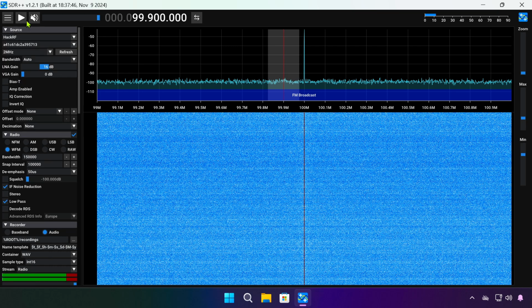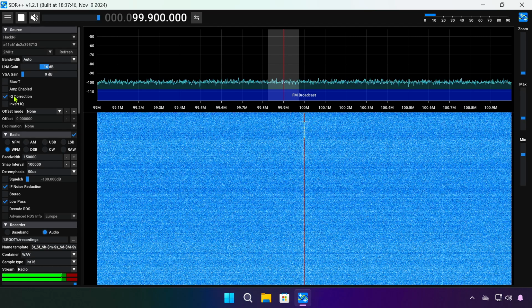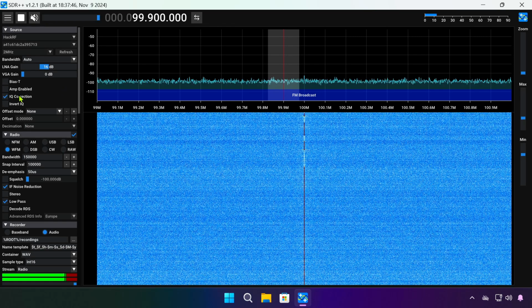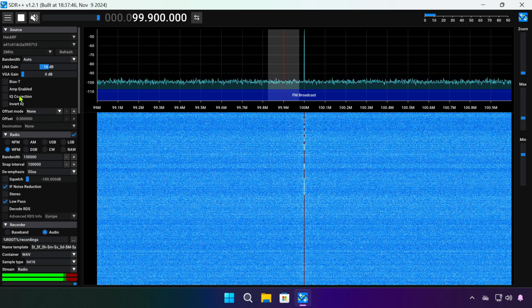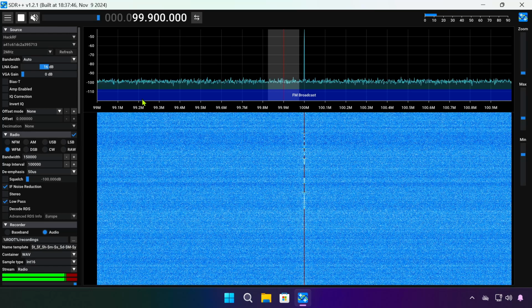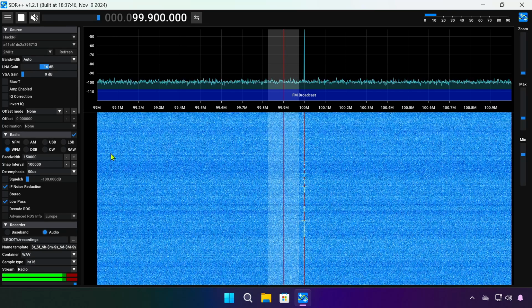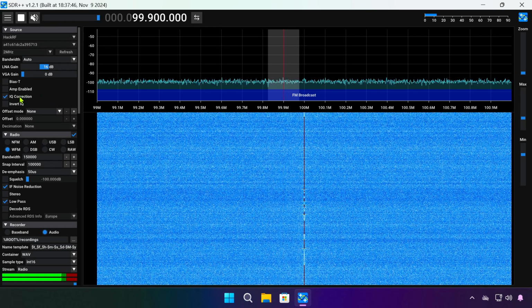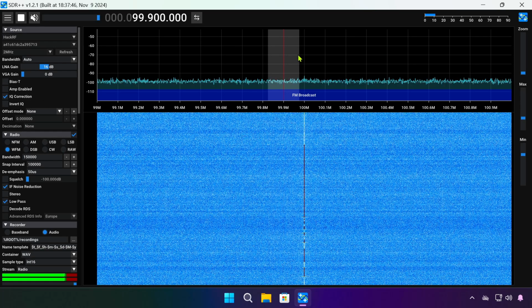Now let's go back to HackRF and enable IQ correction. Disable it, enable it. Now you see the spike here? So this helps with the DC spike appearing on this frequency display. It can also help with, as I said, imbalances that impact things like reception and audio quality. And to adjust it, you simply tweak the value until the spike disappears or moves outside the range you are tuning to, called VFO's passband.